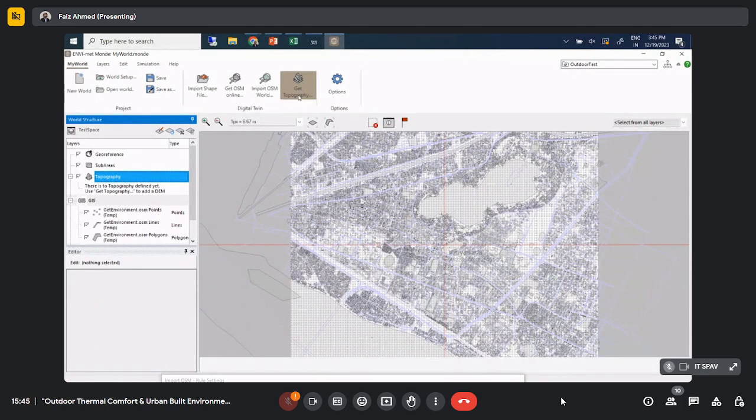Don't build up the entire 50, 50, 35. If the entire grid size is 50, 50, 40, we should be building about 40, 45, and maybe 20 to 25 meters in height. One third should be left free for simulation, otherwise we'll have errors in the model. But these possibilities are there.